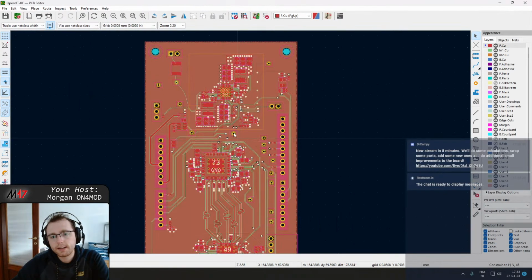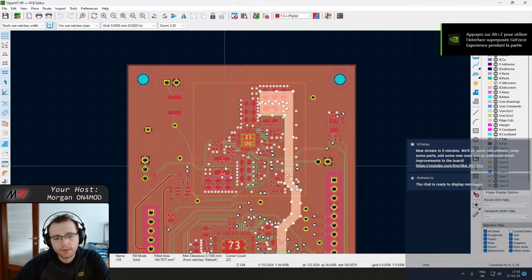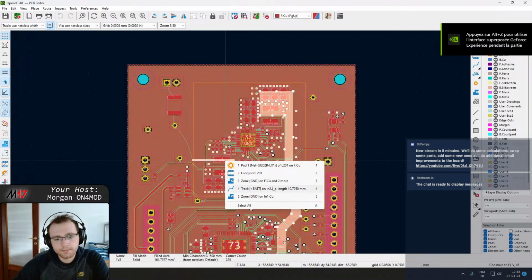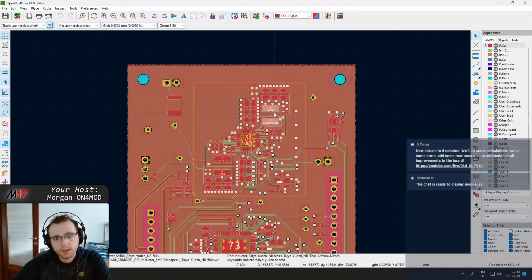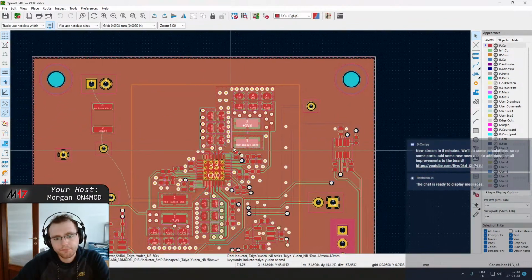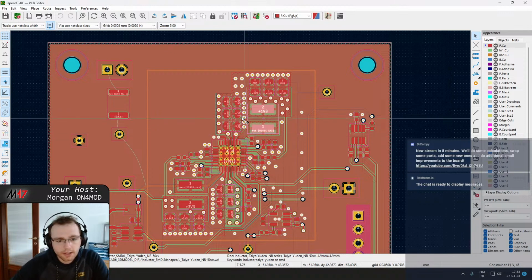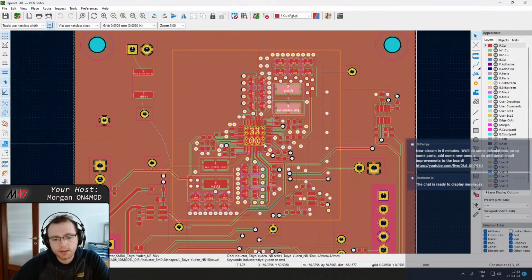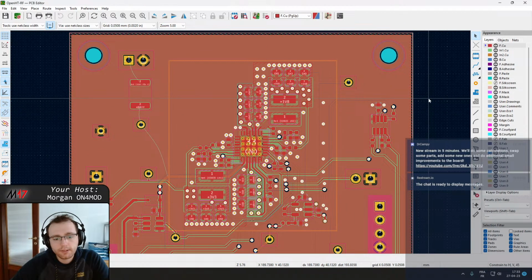Last time I discovered that the two inductors that I use for the power supply, so that is that one and that one, are now not recommended for new design, and so I would like to change them. I had a quick look previously, and it seems that they do have components from the same manufacturer, the same value, the same footprint.